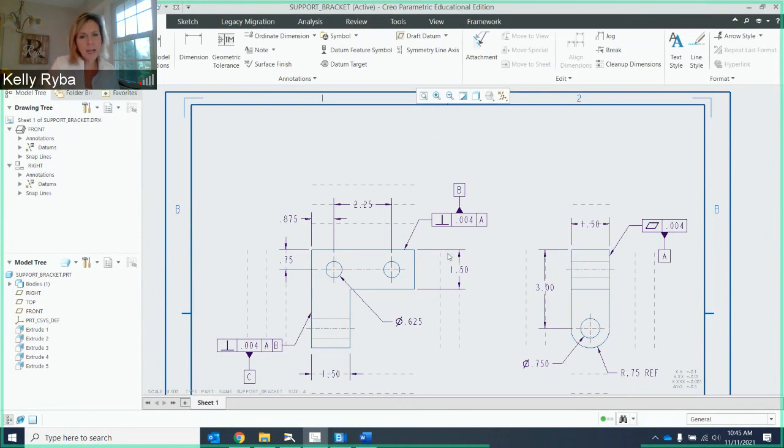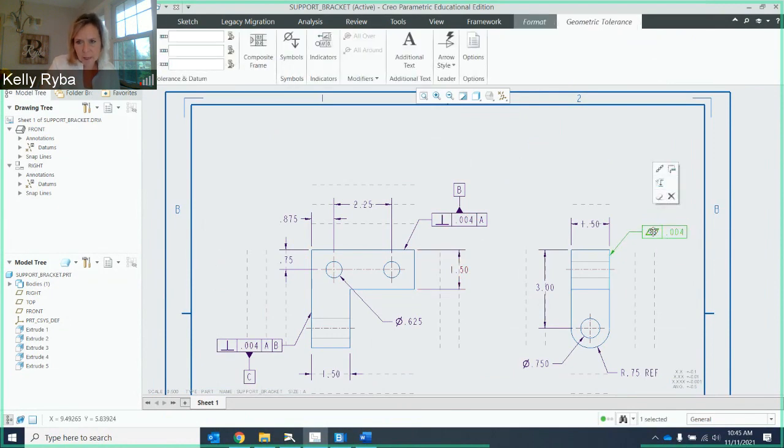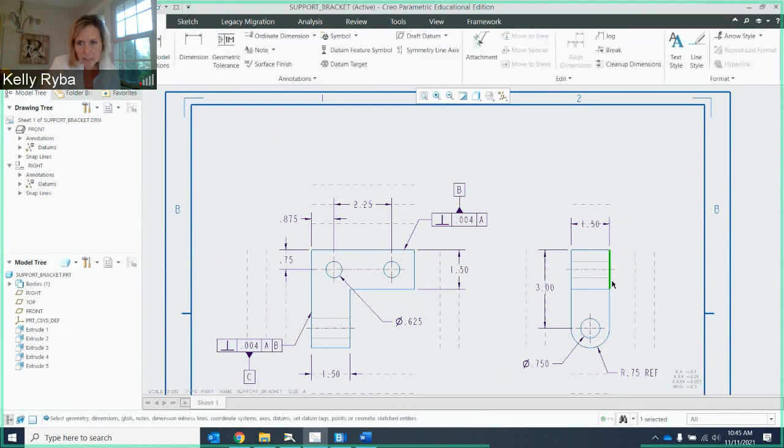It's not wrong to add it to the surface separately, as you may see sometimes, but it's better if we do it this way because it's giving us that order of operations. Once it's perpendicular or once it's flat, it's now going to be a datum for something else, okay? So this is the better way to do it. I'm going to move this one down. Okay. Use the attachment. Make it more on that surface. There we go.